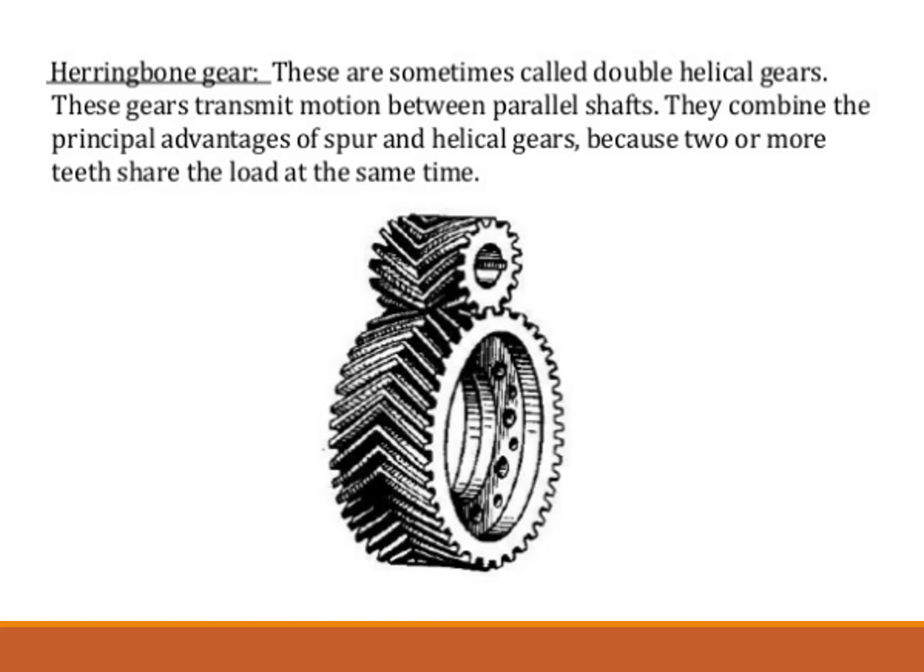Herringbone gears. A right and left hand helical gear side by side form the herringbone gear. Originally, a herringbone gear consisted of two helical gears, one right-handed and the other left-handed. But today, most herringbone gears are produced as a single unit on special machines which cut the teeth in two directions at one time. The herringbone style neutralizes the end thrust and makes a strong gear.